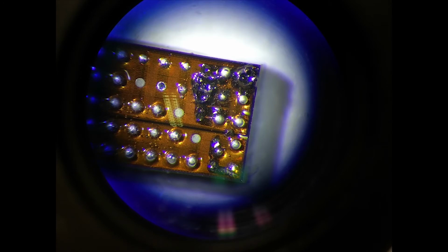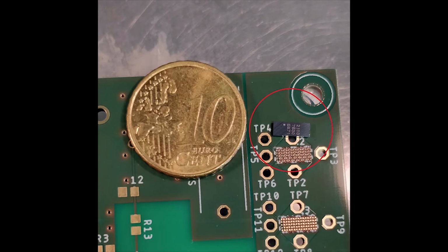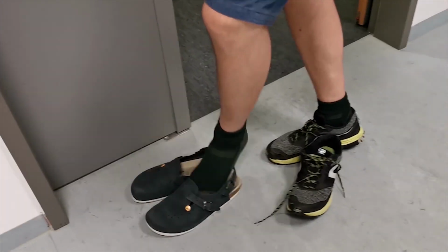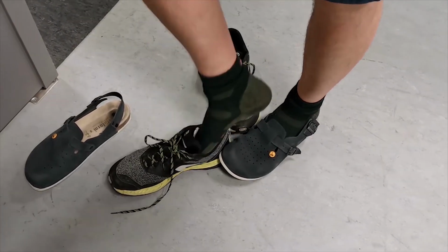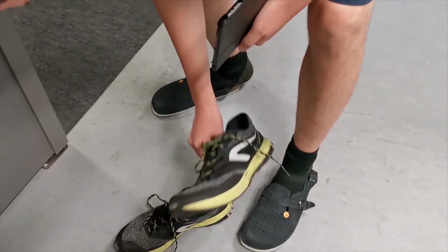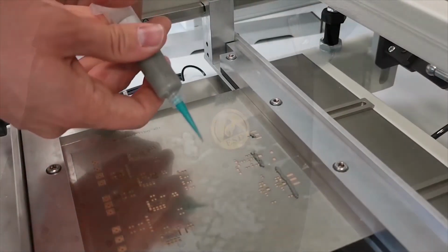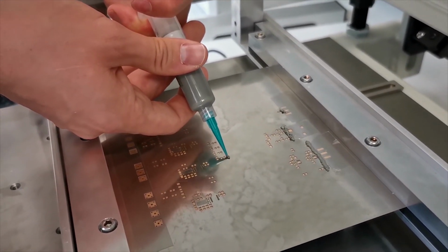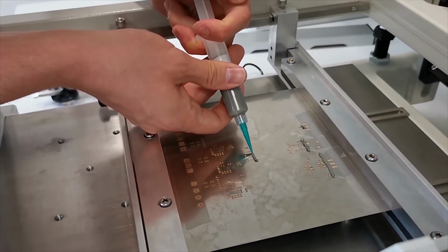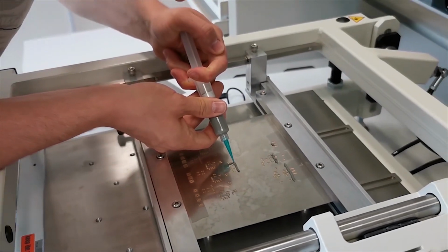An especially big challenge was to solder the GaN device, which has 75 pads on the bottom side with a pitch of 200 micrometers. After the schematic was finished, we started with the manufacturing process, which is shown by the time-lapse in the background. For our first PCB, it took us over a week to figure out how the process parameters are optimized.